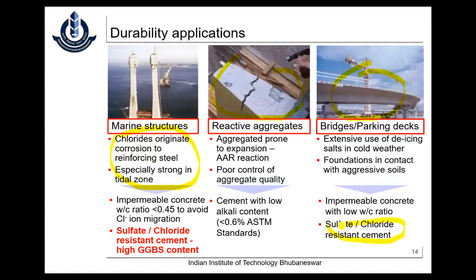Now we're not having all these sulfate resisting cements. We have only two cements, either the fly ash based cement or the slag based cement. You need to test these products before you go ahead. This is what I want to emphasize as requirements.